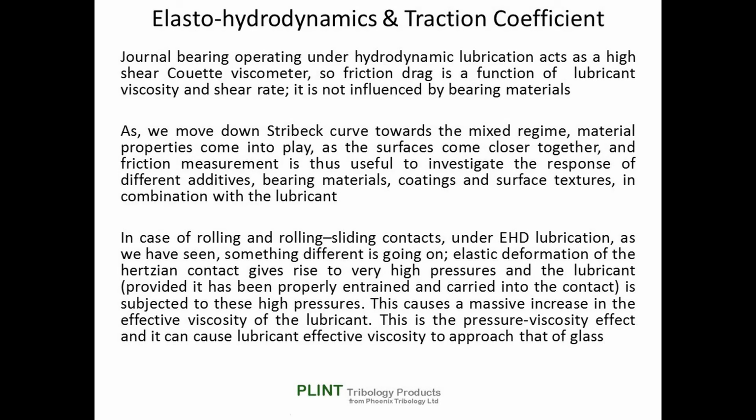But why is this so important if we're only interested in friction or traction in a contact running under EHD lubrication? A journal bearing operating under hydrodynamic lubrication acts as a high shear Couette viscometer, so the friction drag is a function of the lubricant viscosity and the shear rate. It is not influenced by the bearing materials.